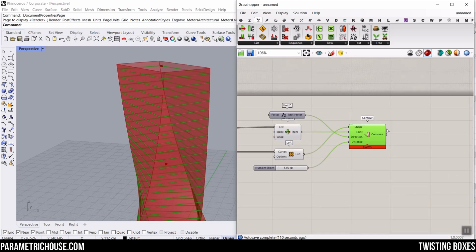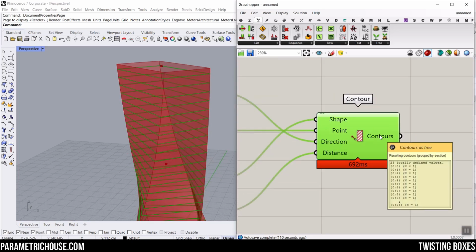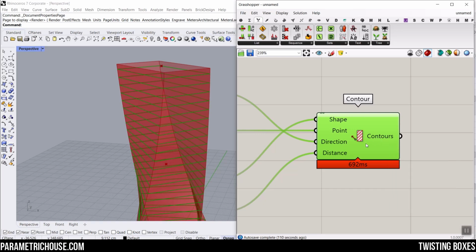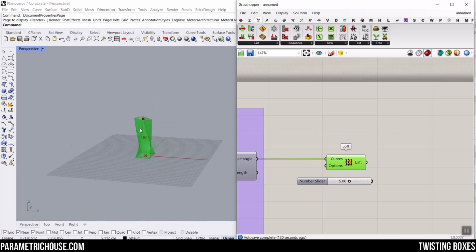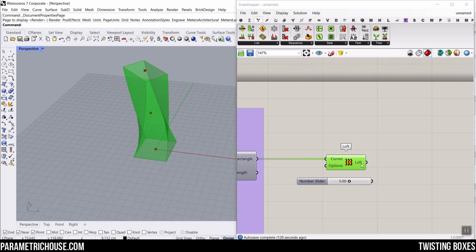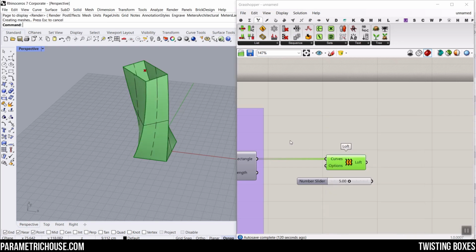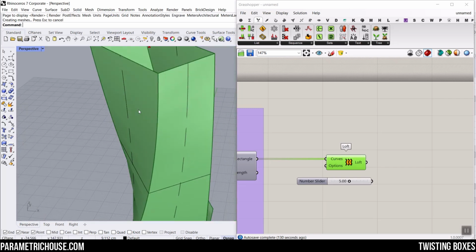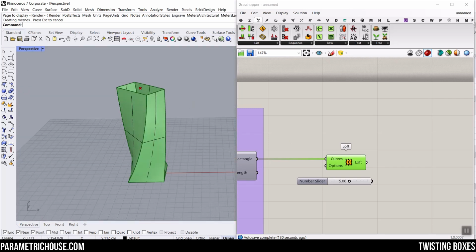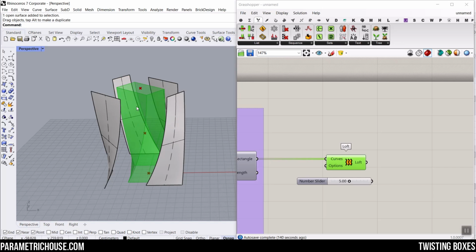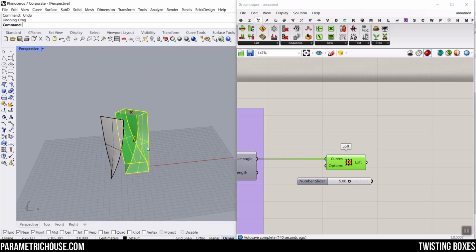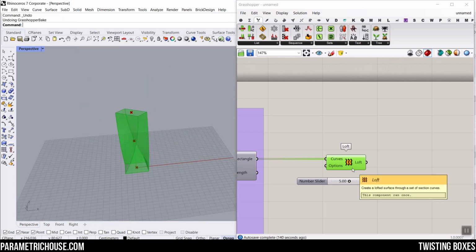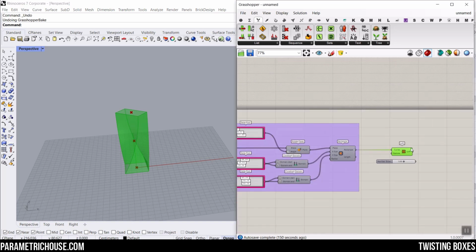I'm going to show you another technique, and we're going to talk about this in the advanced lesson in the course. So if you want to learn more about it, you can enroll in our course, okay? So a faster way to get results is to convert this loft. You can see it's like a polysurface, right? 4 NURB surfaces connected together. So what I have to do is to explode that and work on any of these NURB surfaces to extract the U direction, right? To extract the boxes. That's the fastest way of how you can change the box and also extract the curves.